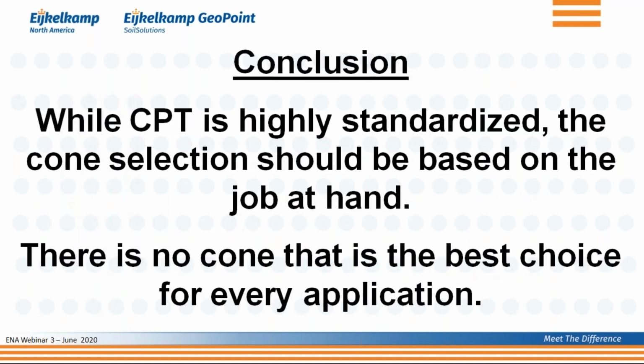So with that, we come to the conclusion, and there are really two parts to this whole thing. First of all, what you need to remember is that CPT is a highly standardized test method, and because of that, we can correlate the readings with the soil behavior. At the same time, there is no test method, not even CPT, and I'm a strong believer in CPT, that is the best choice for every application.